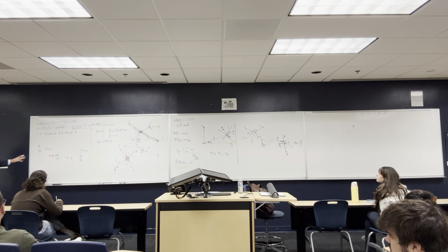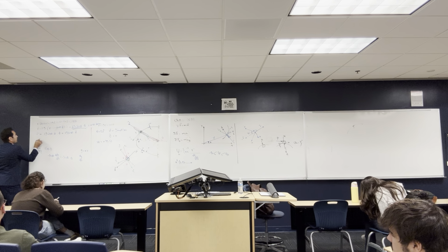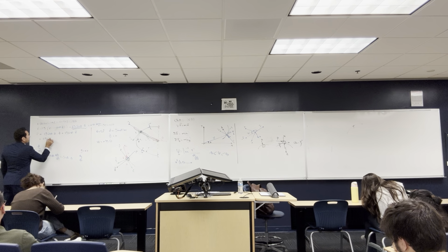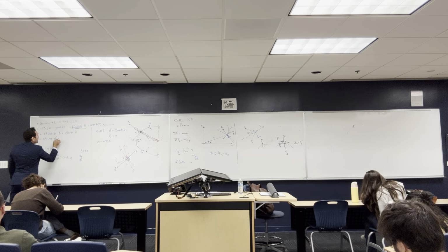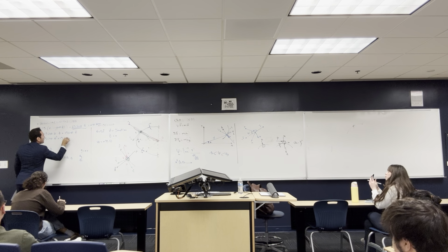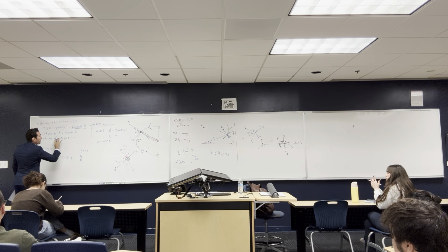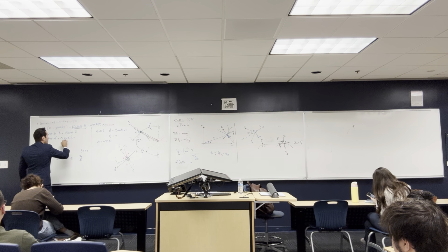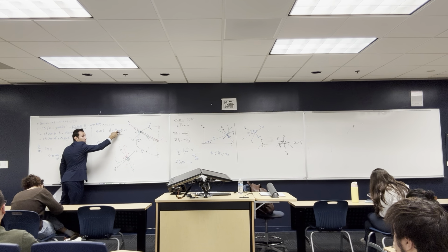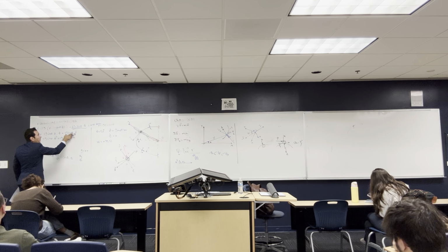Okay, so this is going to be equal to 1.5 cosine theta times theta dot squared, plus 1.5 sine theta times theta double dot. When you substitute here, theta double dot is equal to 0. That's why, when I told you, if you substitute with this part as a constant, this part is definitely going to be 0. And I can find this part is going to be equal to negative 18.75 feet per second squared.